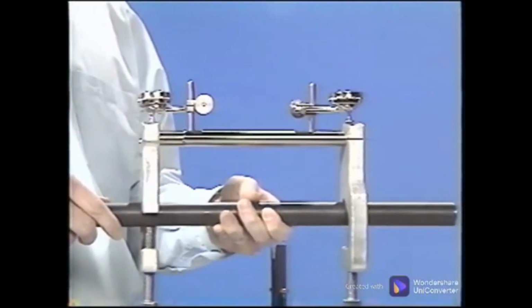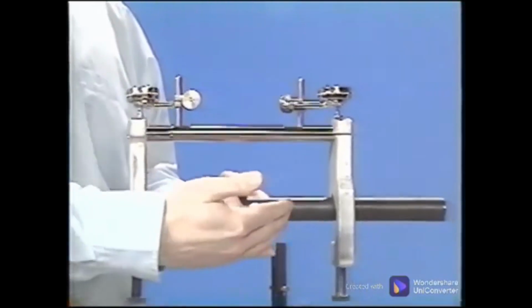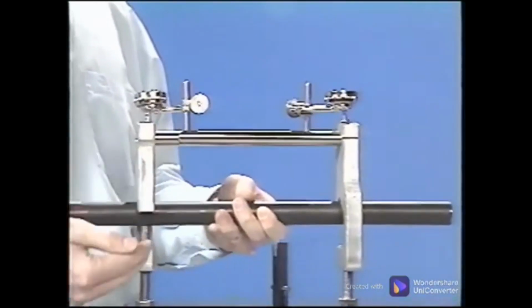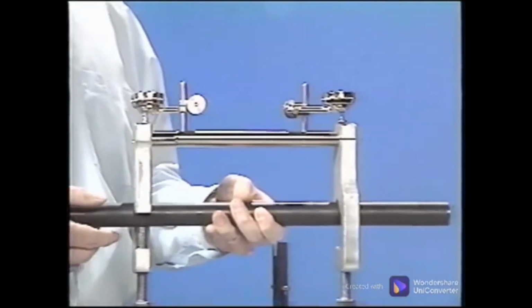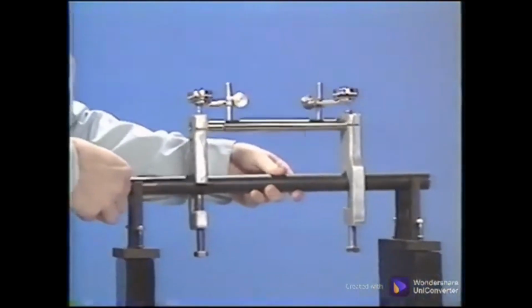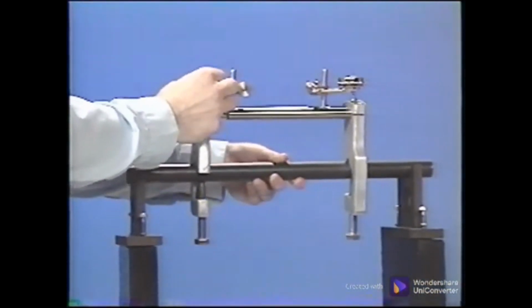To measure bar sag, extend the bar to the length it will be used during the alignment process and mount it onto a mandrel or straight section of pipe.